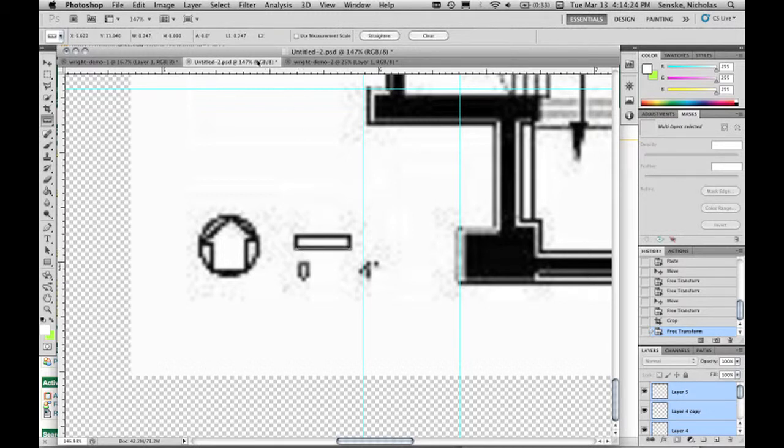Let's find that scale piece again and take a measurement. So almost 0.25, pretty close. So that should tell us, again, if we're 16th scale, then a 1/4 inch should equal 4 foot, and it's pretty darn close. Good enough. Okay. Again, if you wanted to change the size of this to something else, once you have it at 16th, you could double it, and that makes it an eighth. Let's zoom out.